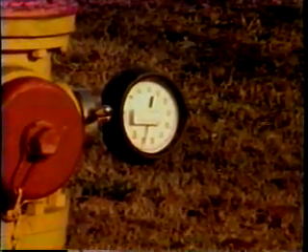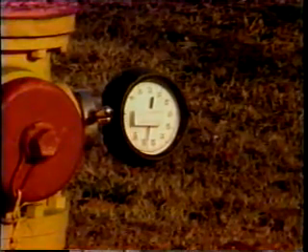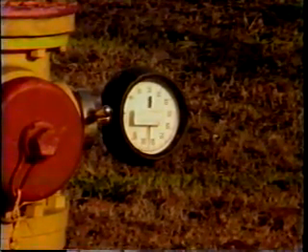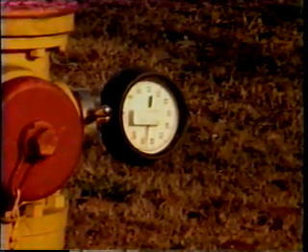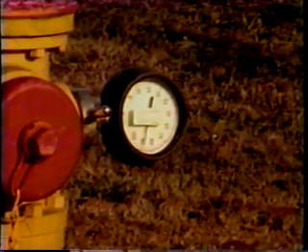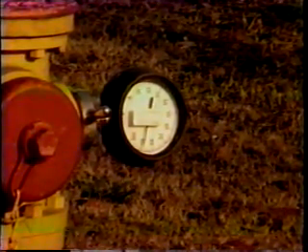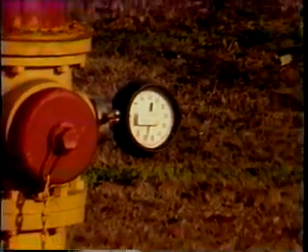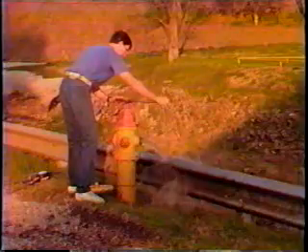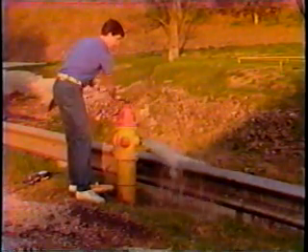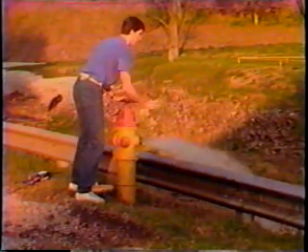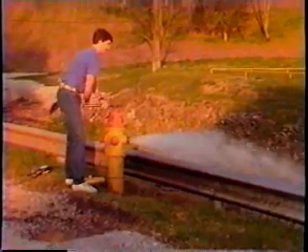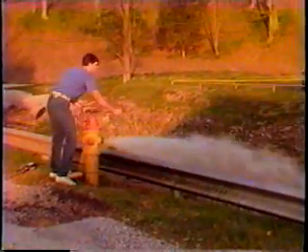Before we talk about what we're going to measure at a hydrant flow test, it's necessary to understand two terms, residual hydrant and float hydrant. The residual hydrant is the hydrant at which pressures are measured. The second type of hydrant is the float hydrant. At the float hydrant, only the discharge from the hydrant is measured.